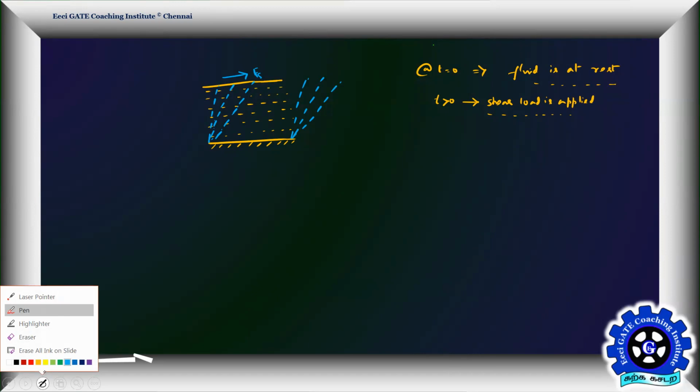Now, if I go to a later time, say t1, t2, t3, whatever, greater than 0, in the fluid the shearing will happen similar to your solid body. But there is a little difference between the previous solid and the present fluid. It starts to deform continuously. Irrespective of the amount of load you have applied, whatever the minimum, it just slowly deforms, continuously deforms.